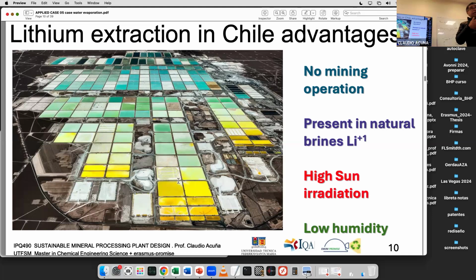But if you go outside, you feel cold because you're evaporating more water. But if you remain in the bathroom, it's not cold because everything is saturated. You do not evaporate water. Your body is not being cooled. So when you have very low humidity, the gradient for mass transfer is very high. Understand? You cannot dry something with saturated air.